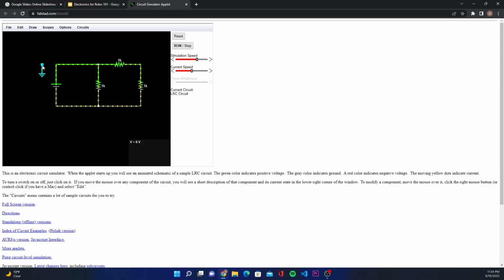We can also see what happens if we put that there. So now this sets this to 0, and now you can see that the voltage at this node is -5, because this has to be 5 less than this because of this voltage source. So we can move it from here and see that this is 5, because this node has to be 5 greater than this one, right? And moving it anywhere along this node is the same thing, because they're the same node.